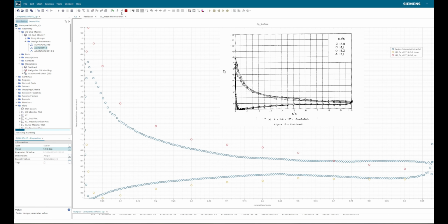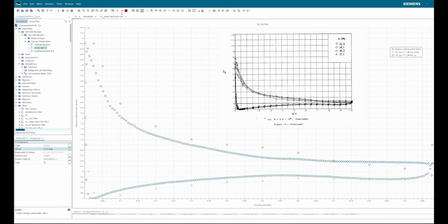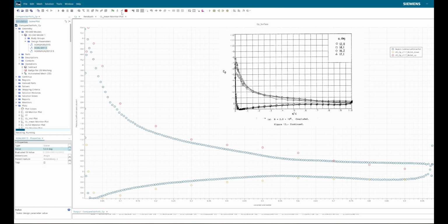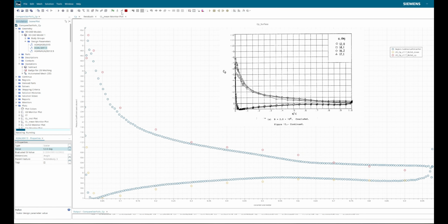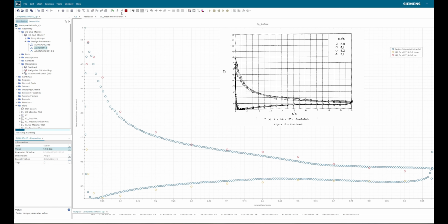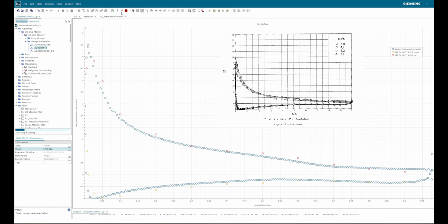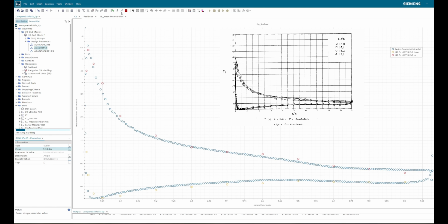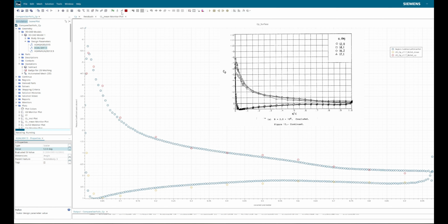In the wind tunnel test, the Reynolds number was 2 times 10 to the power of 6. Considering standard atmospheric pressure and reference air density, I used a flow velocity of 29.2 meters per second per unit chord length in my simulation, which is also within the expected speed range of my small aircraft.